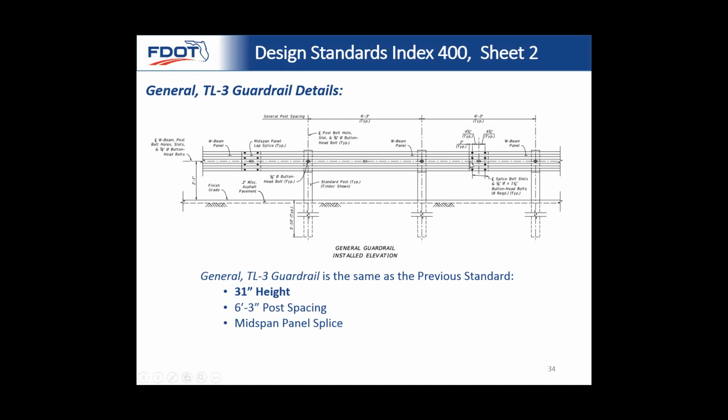When you get a splice right here at the post, it could end up just tearing in shear, and that's not good. So in order for this to work the most efficiently, it's at midspan, and then you're always getting a tension type of failure, and it's a lot stronger in tension than it is in shear, like this.